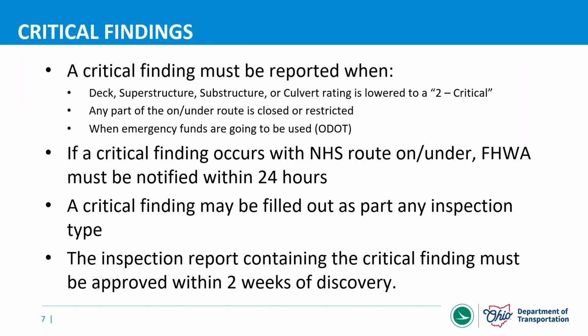A common one we've been seeing on the state side is bridge impact. An overhead bridge is impacted by something on the under route. If we're closing either the overhead or the under route because of that impact, it's going to be a critical finding. And the last bullet here is mainly for ODOT program managers, but when an incident happens where you are planning on using emergency funds, we would like to see that filled out as a critical finding as well.